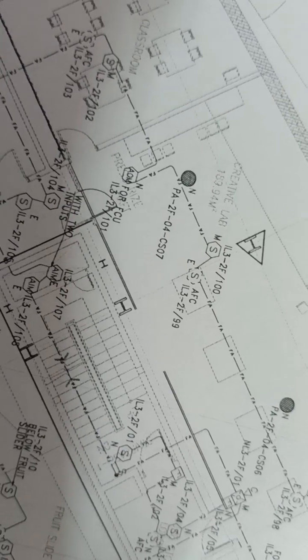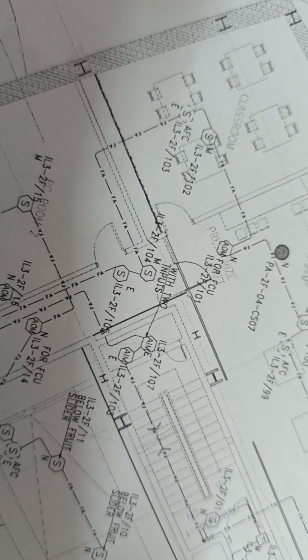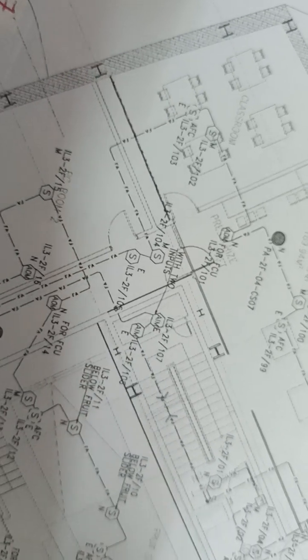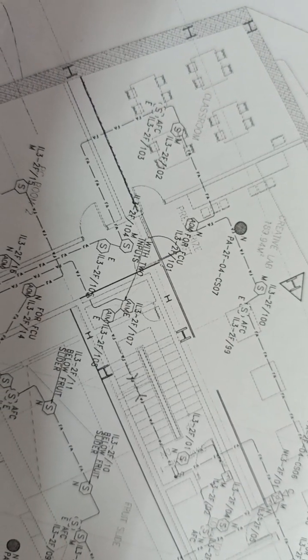From another it will go on, and if some modules are there, in between you can keep them in a loop. But the sounder should be on a separate circuit, because the sounder requires more decibel sound, so the power supply will be different for that one. That's why we use a separate circuit for the sounder and a separate circuit for the smoke detector.